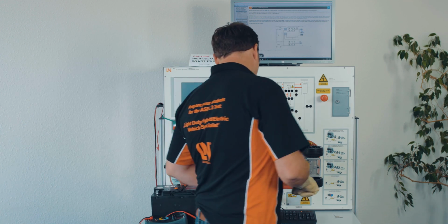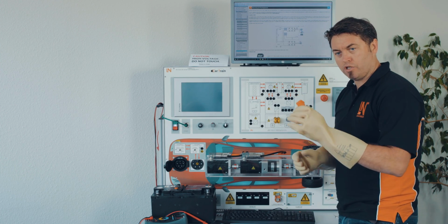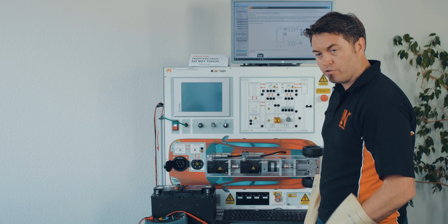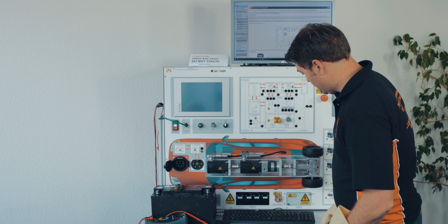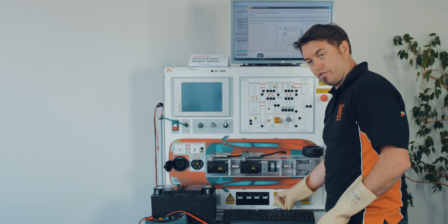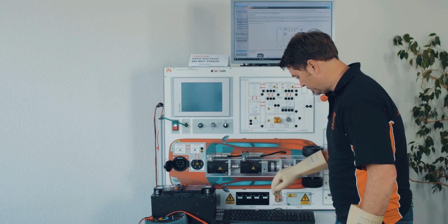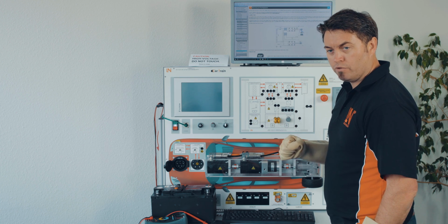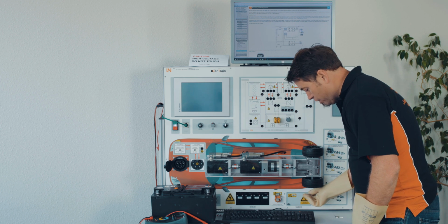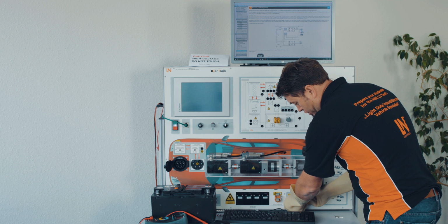Now we can go along and find the service plug, and we can disconnect the service plug as well. Again, if you've got a lockout box, it goes into the lockout box or it goes into your pocket somewhere. Some manufacturers will tell you to insulate the connector left on the vehicle as well, so get some insulation tape and wrap around it. It's up to you, up to what you're required to do. Now, on every vehicle there will be a measuring point where you can go along and measure a connection.